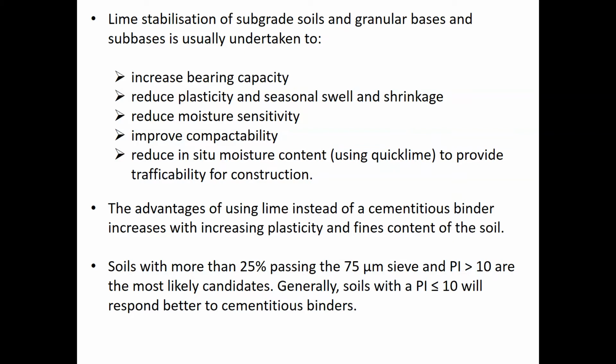So they would rather just have the access road trafficable. Then they only do the roads at the end of the projects. So lime actually can do that. Lime, if they can strengthen the subgrade, or in certain cases, if the road just has the sub base put in, then they can do the cement or lime, usually a cement stabilization for the sub base.